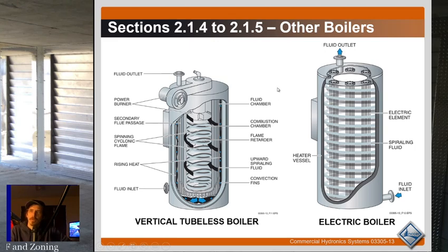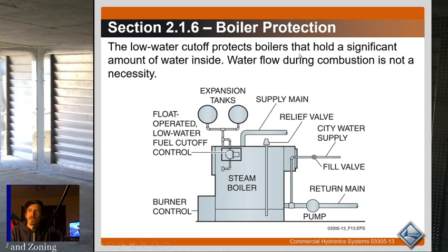but they work okay. Alright, a low water cutoff protects boilers that hold a significant amount of water inside. Water flow during combustion is not a necessity. Alright, so they're talking about steam boilers here. This is very critical on a steam boiler, but a low water cutoff is also required on a hydronic, water boiler if you don't have a flow switch.